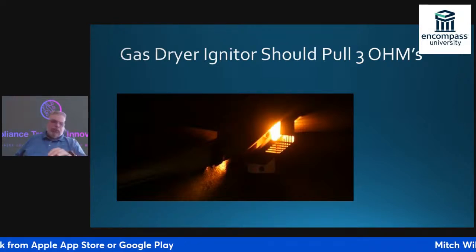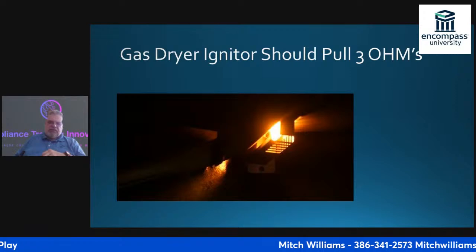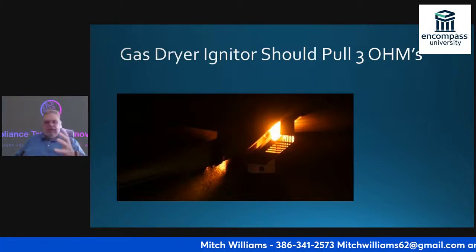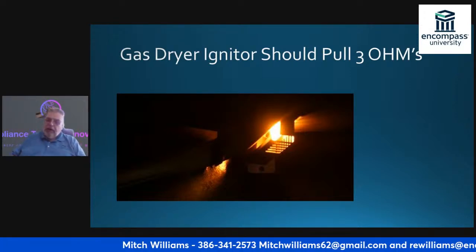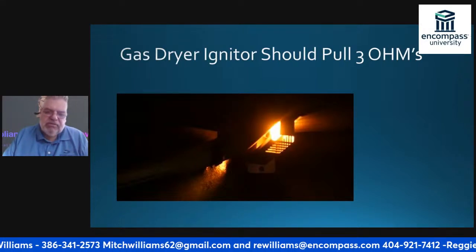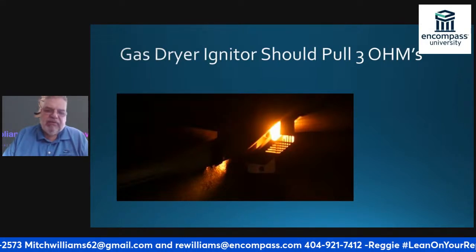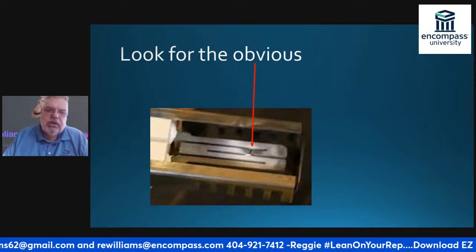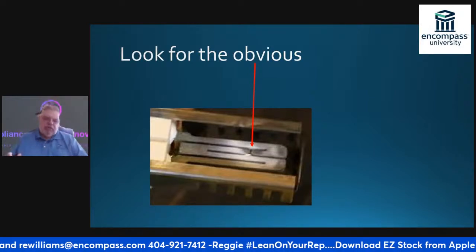If I do not get a beeping, that tells me that I've got to replace the gas valve. That's about it on a gas dryer. Then we're going to go and check some of the other things. If that checks good,